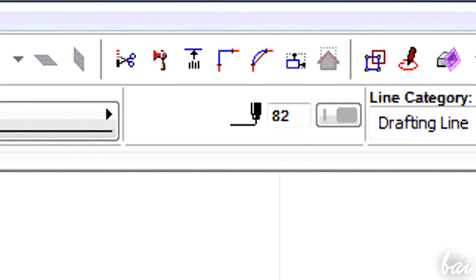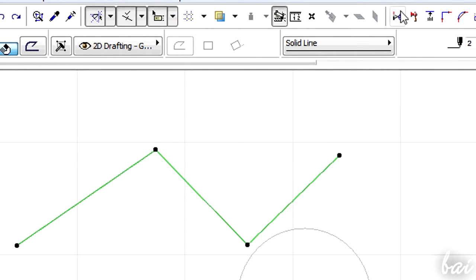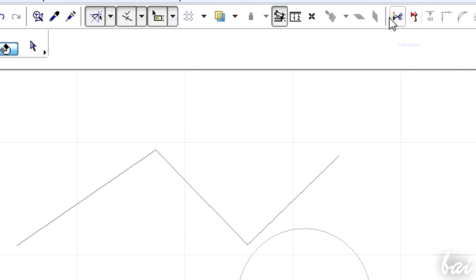There are other edit tools on the standard bar. Use the Trim button to cut off parts of the line delimited by 2 black points. You can quickly activate it holding Ctrl down. The pointer will turn into a scissor.